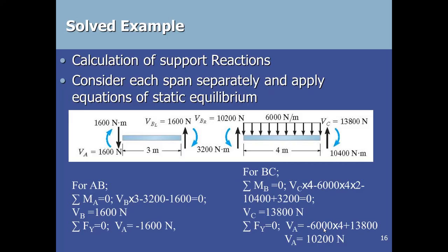Now we calculate the support reactions at these supports. For that we will consider each span separately, because if you look here, these are the moments, the values you calculated here. So we have these values, so just show the proper directions for these moments. And now we will calculate the reactions by applying equations of equilibrium.